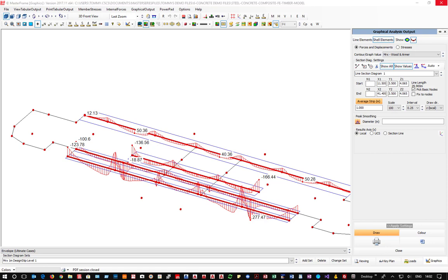And personally at the moment there are 1 or 2 reasonably respectable spreadsheets out there by the Concrete Society that will allow you just to take what the reaction was in that column and what the loading is on the floor, and do your punching shear checks very, very quickly.